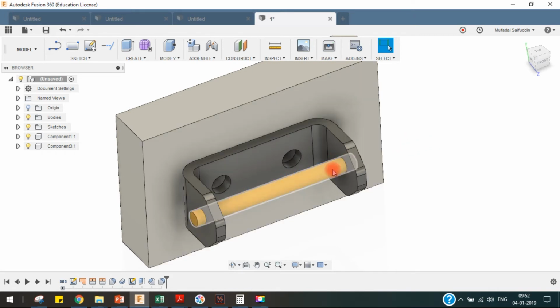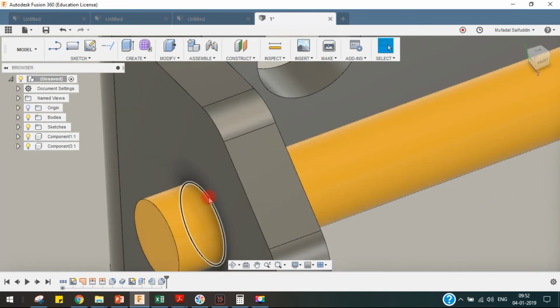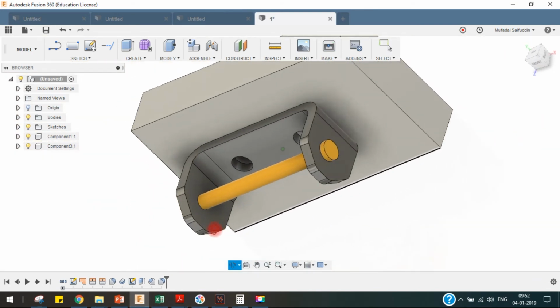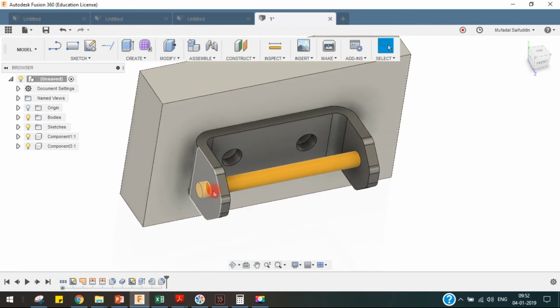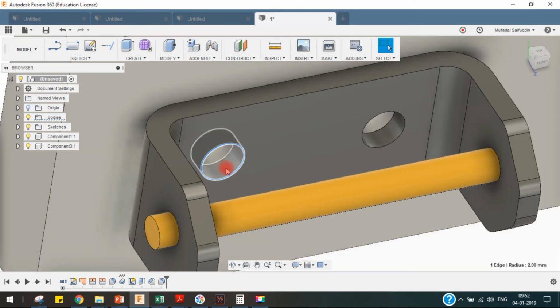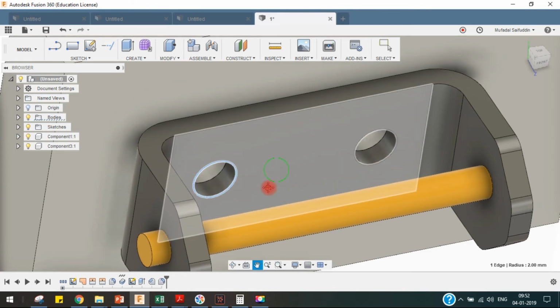Although there are additional considerations of assembly, for example, the dimension over here, the diameter is generally decided based on the type of fit which is required between the pin and the bracket. So if it is lesser, then there will be an interference fit. That is what is implied over here, because there is no bolting arrangement shown over here. And the other thing is the dimension of this mounting hole will be generally higher than the dimension of the bolt, because this is a clearance hole and when using a floating fastener assembly we need to have a clearance fit. So those 2 are other considerations for this simple bracket.